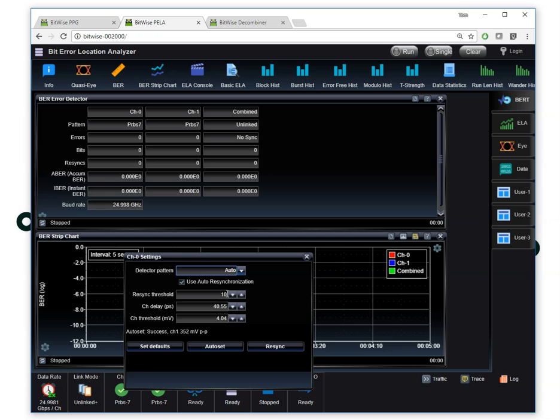These words are 128 bits each. And if it sees 10 words in a row that have errors in them, it'll think that it has lost sync, and it'll go about finding sync. If that sync is in auto pattern mode, it'll first try the pattern it was in last, and then it'll go about also searching patterns, and then also searching inversions of patterns. And so in a blink of an eye, it'll find the data that you're using.